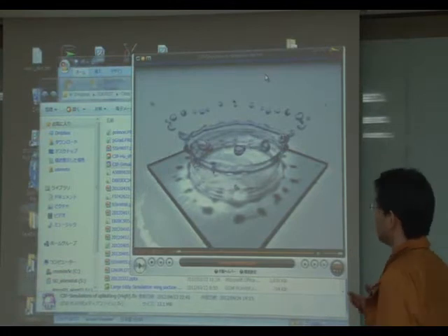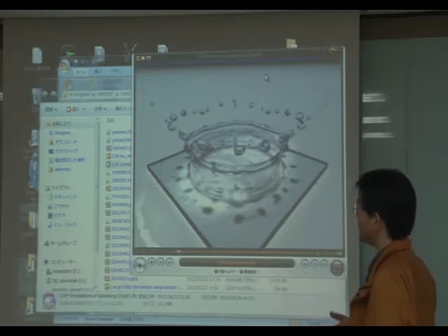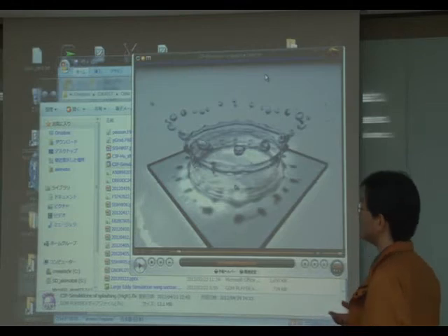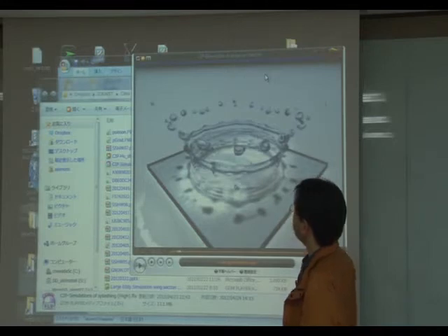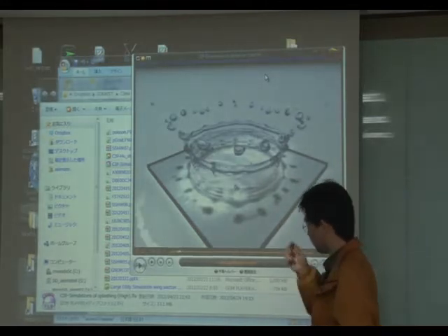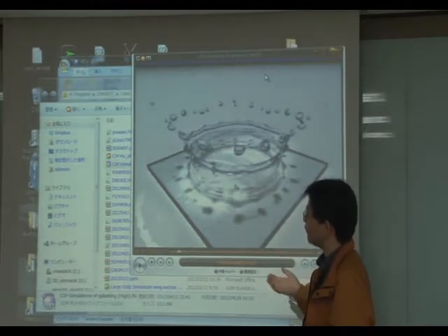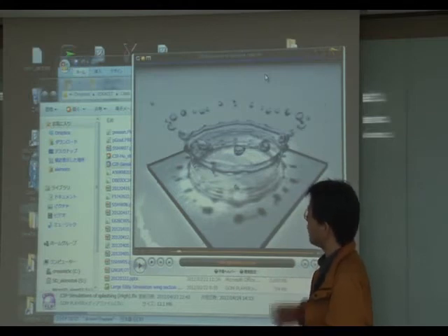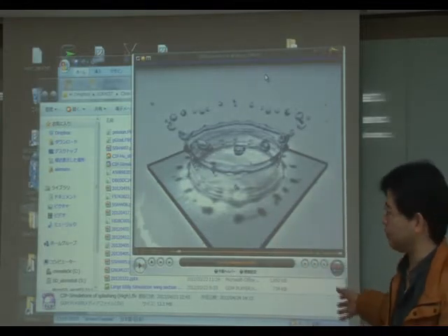So CIP is actually only the treatment of the convection term, but if it is used with a free surface capturing method, like marker density function or VOF or level set function, it will give a very powerful solution of free surface problems.